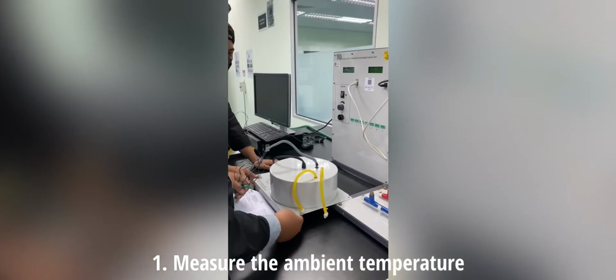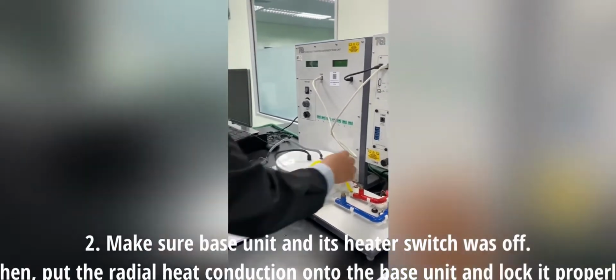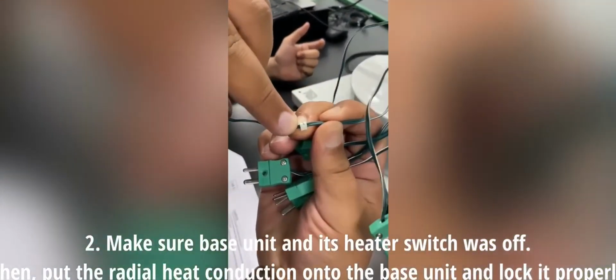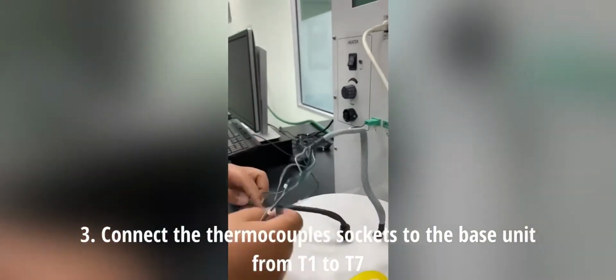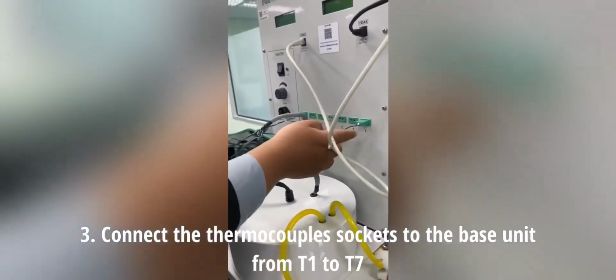For the procedure, firstly we need to measure the ambient temperature before starting the experiment using a thermocouple. Make sure the base unit and each heater switch are switched off. Then we put the radial heat conduction experiment onto the front of the base unit and lock the unit properly. Then we connect the thermocouple sockets, each socket to the base unit. Follow the correct number from T1 to T7, and then the heater cables are also connected to the base unit.